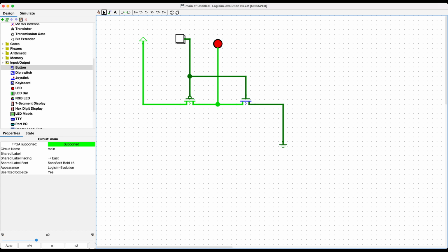Microprocessor fabrication is somewhat similar in the sense that you deposit material and then selectively remove parts of it. The way you selectively remove parts is you put down a layer of material, and say you want to etch a pattern into it. You make a paper cutout that has the pattern as holes and the complement of the pattern as the paper.